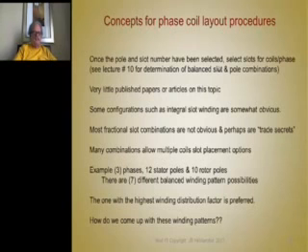But anyway, at any rate, some of these fractional slot combinations have a multitude of winding patterns. For example, this 12 slot stator and 10-pole rotor for 3 phases has 6 different winding patterns possible for balanced 3-phase windings. Only one of them has a very high winding distribution factor, and so how do you find that one?